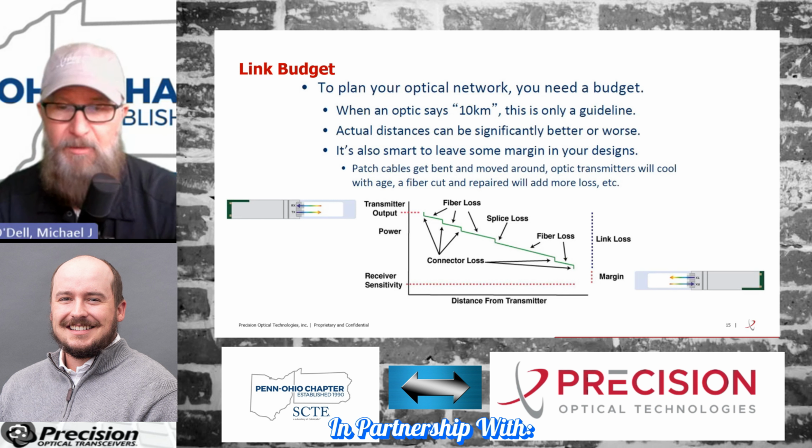And to your point, the other considerations are, what is the data rate that you need? How far are you going? And then at some point, you have the Goldilocks zone that you mentioned, which is the receiver sensitivity. You can also overpower a receiver, right? If you have too little loss and too much light, you could potentially damage your transceiver.